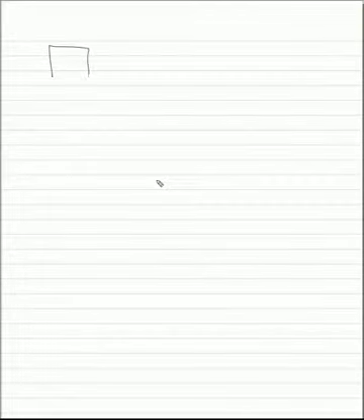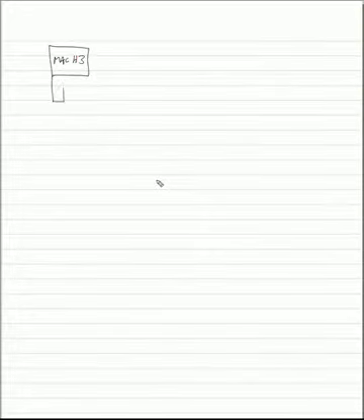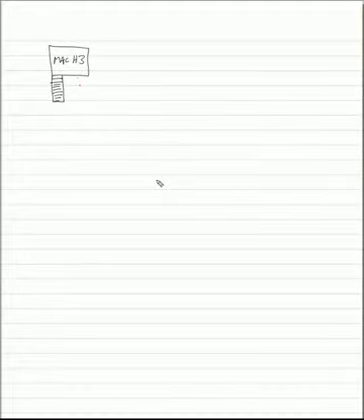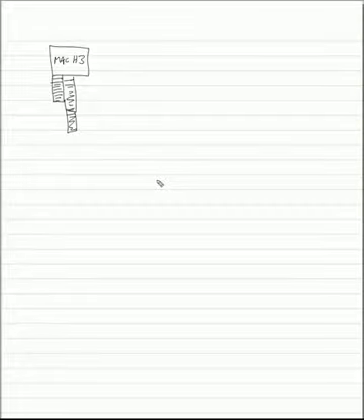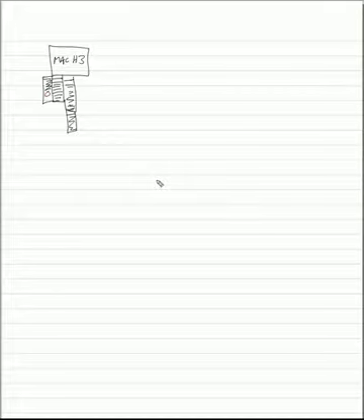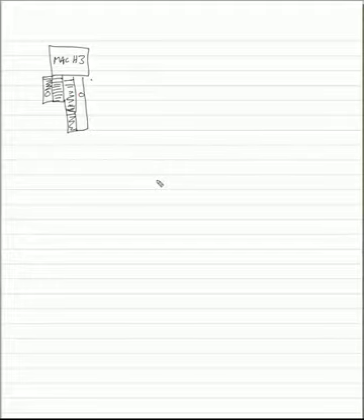This video is going to explain a little bit about serial plug-in ModBus. As I've shown before, when you have Mach 3 running, you have a serial ModBus with 128 16-bit input registers. You also have a TCP ModBus with 1023 registers for input. The serial also has 128 registers for output, and the TCP also has 1023 registers for output.